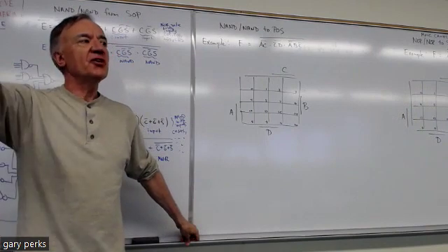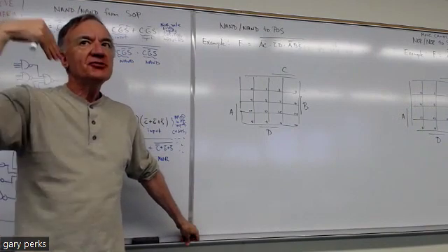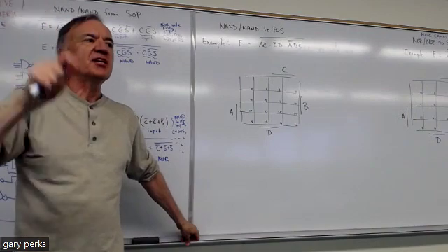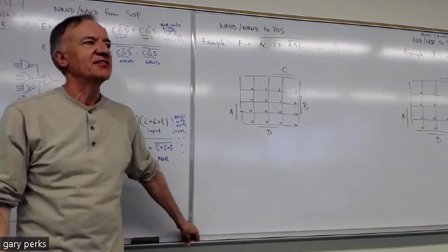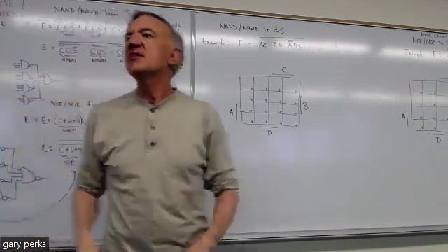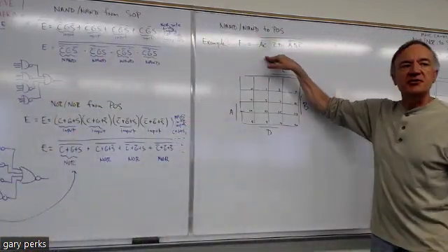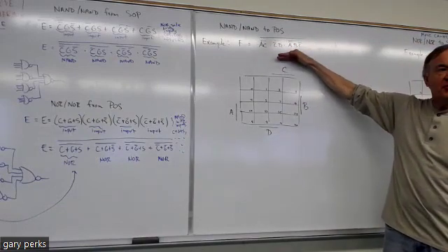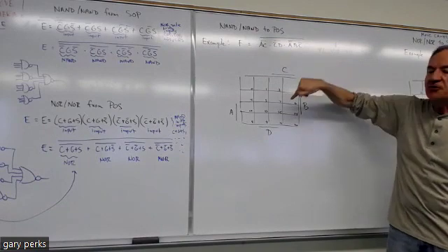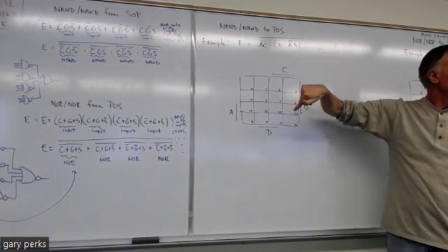And in fact, even when you're going either from a truth table or into a truth table, do you want a POS equation or an SOP? What's easier to deal with? SOP, exactly. So that's what we want to do here first: take this NAND and make it SOP, because then I can go into the K-map easily.